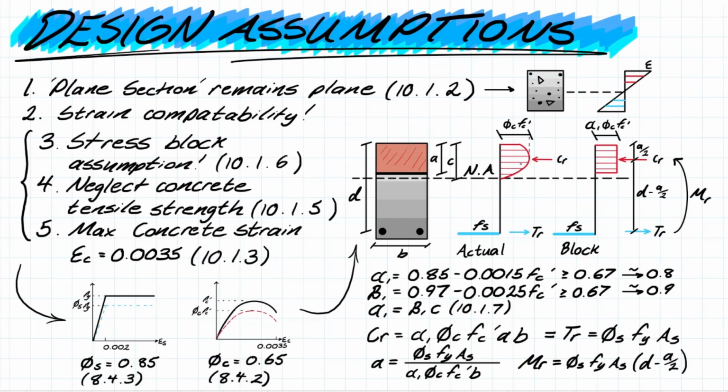We actually have an issue where we have a parabolic shape for this stress strain distribution. And engineers know that anything with a curve is typically hard to calculate for without using things like integration and other methods to solve. So lazy engineers have developed ways in order to make this simpler on ourselves, and that's creating a compression block or stress block assumption. And all that assumption does is takes this parabolic curve and transforms it into a rectangular block so that we can solve for design variables.